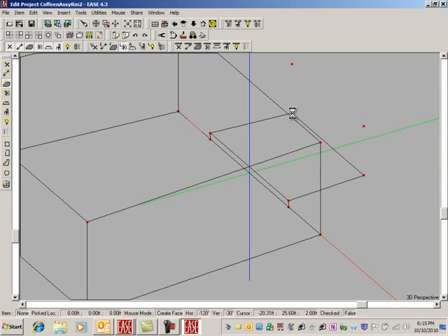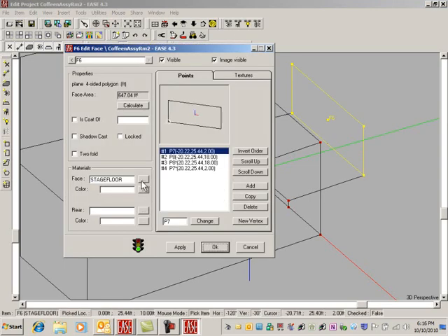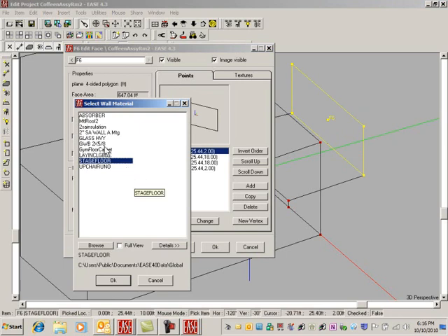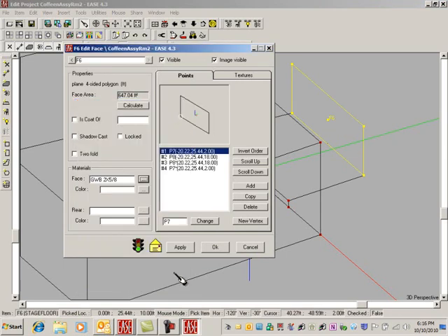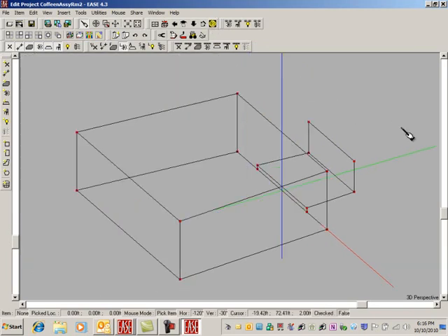Now I could create a wall here. And then add this first starting point for this wall to it. That would make some sense. I could also add that point right now. That point where this all begins is 16 feet from this point. It is simply 16 feet up. If I put a vertex here, I could make a wall that had that vertex in it, and then I could start adding these guys using that 4-degree slope. So when did I do that? I'll take this point and duplicate him up 16 feet. That must be what I did last time, so I'll say, okay.